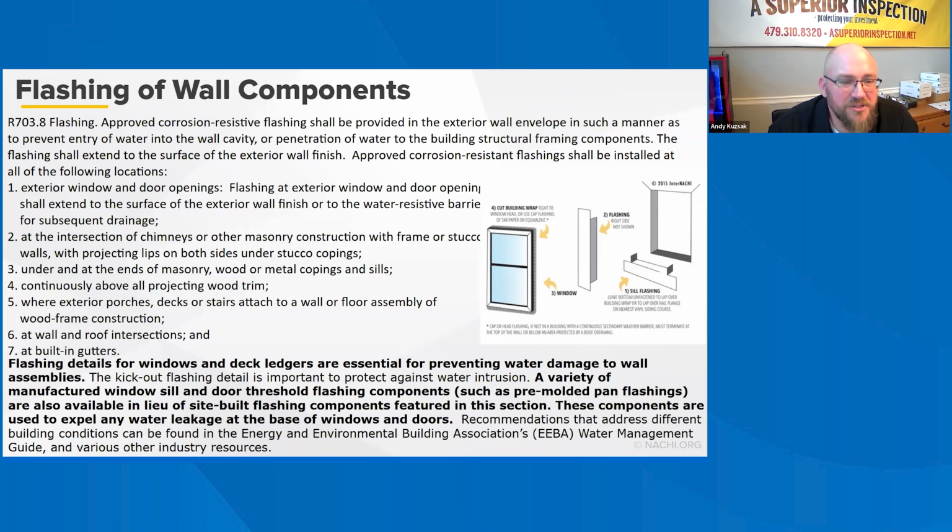And then where exterior porches, decks, and stairs are attached to a wall or floor assembly of wood frame construction, at wall and roof intersections, and at built-in gutters. Flashing details for windows and deck ledgers are essential for preventing water damage to wall assemblies. The kick-out flashing detail is important to protect against water intrusion. A variety of manufactured window sill and door threshold flashing components, such as pre-molded pan flashings, are also available.